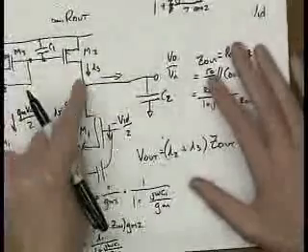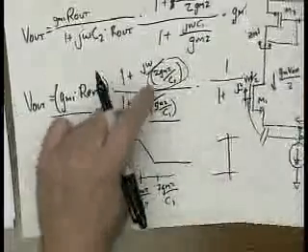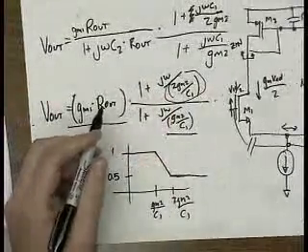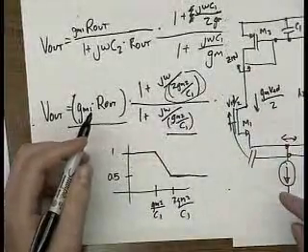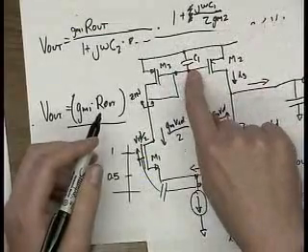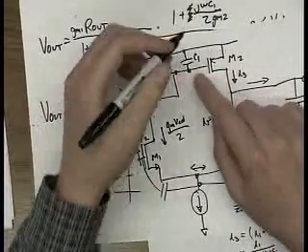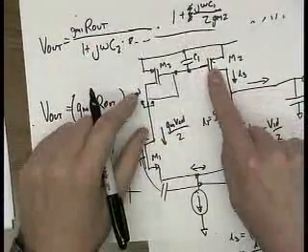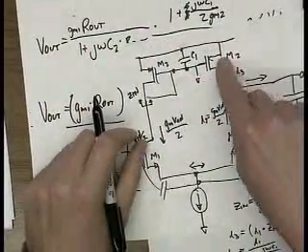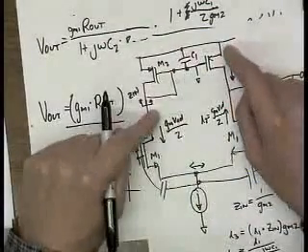You'd say it's C2 times the R out at this node. No surprises there. Now let's look at this pole 0 combination. What that means is that at some point, this voltage is going to stop moving because this capacitor loads down this node. So at that point, this gate looks like an AC ground. That means this always outputs the same current, so this mirror up top stops being effective.